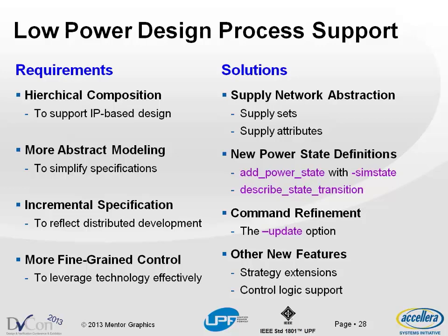New power state definitions based on add power state and the idea of sim states, which allows us to specify what the behavioral impact of the different power states is going to be and use that in simulation as well as in reasoning just generally about the behavior.